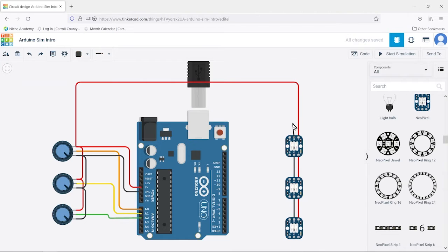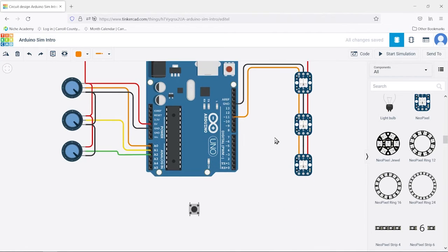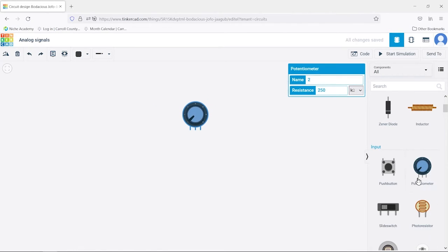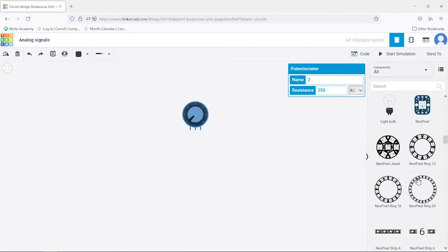It's worth pointing out that Neopixels consume a fairly large amount of power, and there are some design limitations when using these in the real world. If you would like to know more about their use, please Google search the phrase Adafruit Neopixel Uber Guide. It is the definitive source on using these wonderful devices and should be considered required reading when working with Neopixel-based projects.